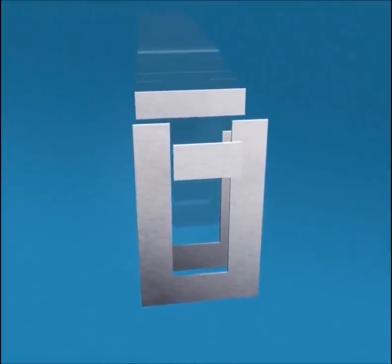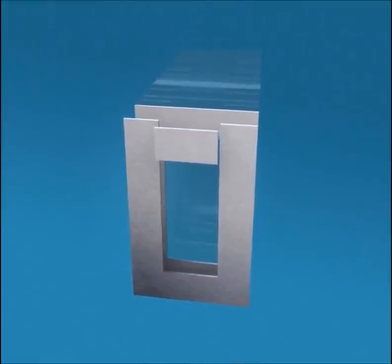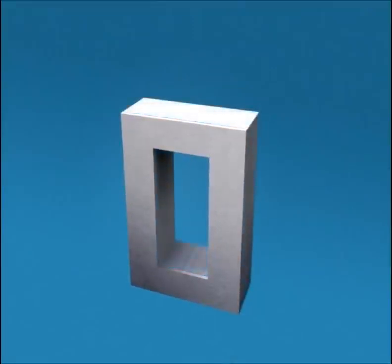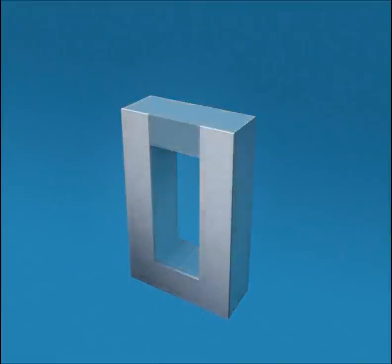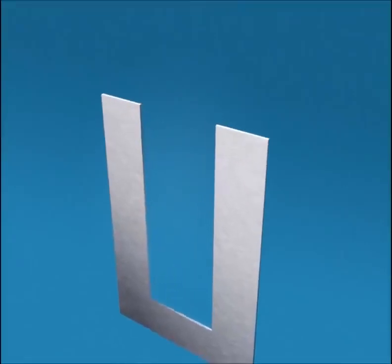To reduce these unwanted power losses, thin steel laminations are used to construct the transformer core. Laminations are made up of highly permeable material, that is silicon steel. These laminations are assembled together to build a solid core. The resistivity of the steel sheet itself is high, reducing the eddy current losses while making the laminations very thin.